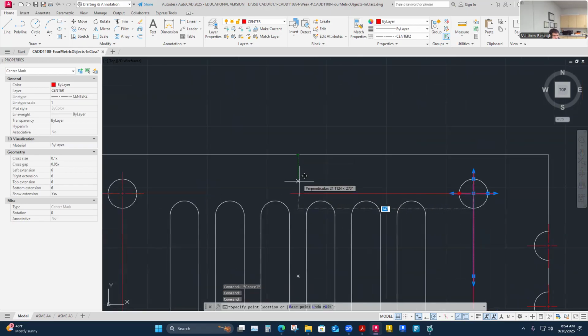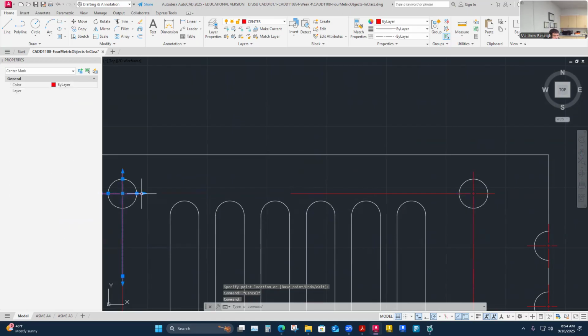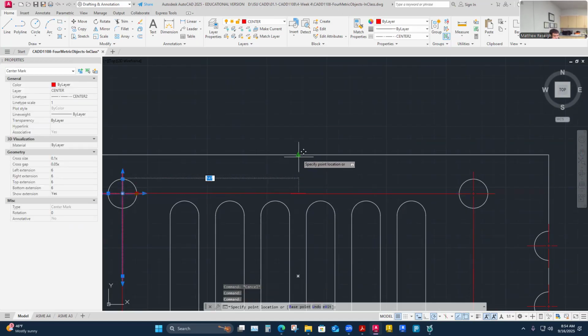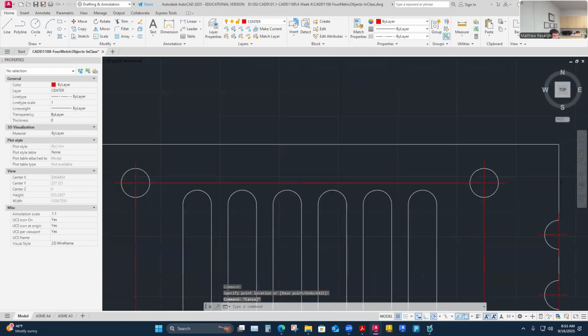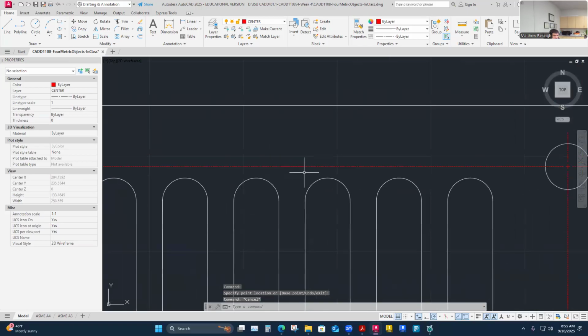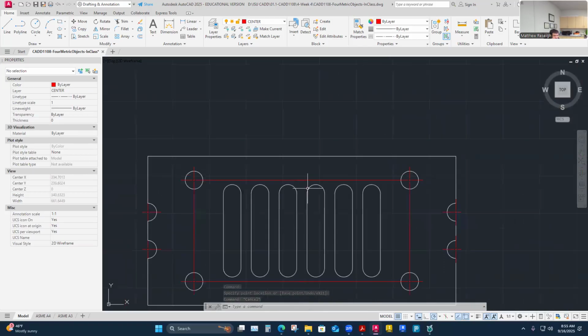So this gets to be a little bit of a busy drawing with center lines. Pull those across. I know there's some overlap there. I just leave it because if it breaks up my pattern on the drawing, it's okay a little bit. I would rather not have a weird gap there, so I always have some overlap. But I'll do that on the dimension lines too when we start dimensioning. Those center lines will reach out and overlap onto the dimension extension lines.